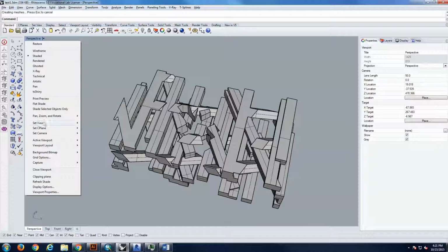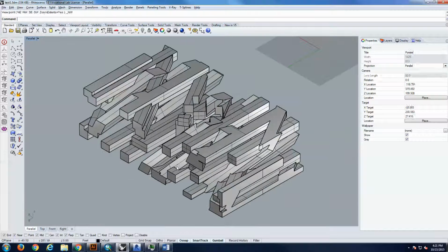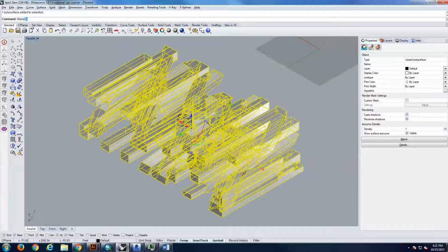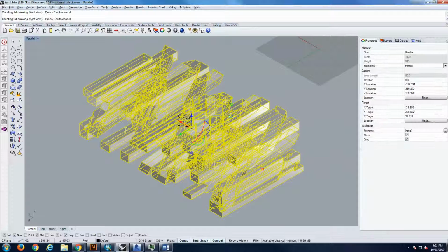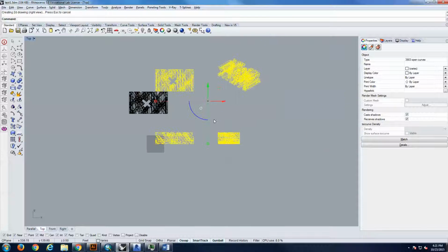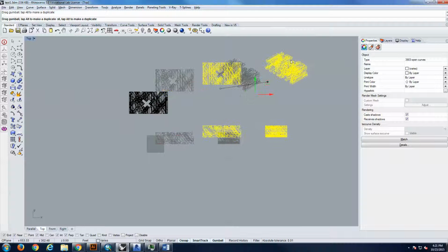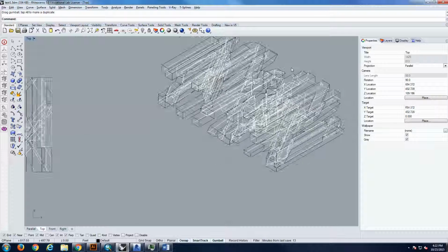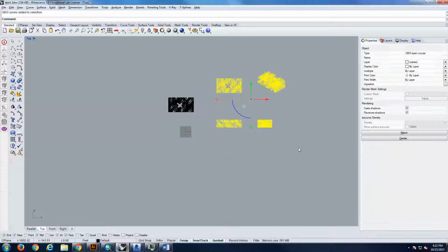So I can go again to my view, isometric, whatever. I do a make2d. I make sure that it has, you know, the views that I always use, hidden lines turned on, etc. And there you have your project. You fix the lines in Illustrator, etc.